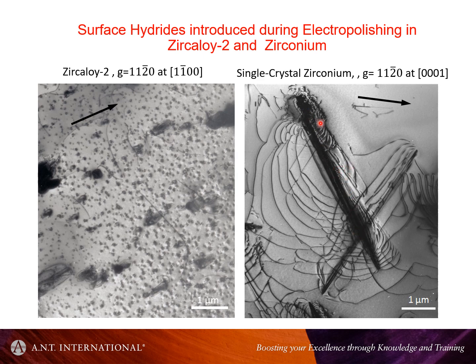The stresses arise because you have a site on the surface which, for whatever reason, is highly reactive, and that's why the hydride forms there: you're creating a lot of hydrogen and pushing a lot of it into the material. So you actually have a source of hydride at this point, and no wonder you get a high stress induced. But that has nothing to do with the bulk behavior of the hydrides. What I've found over the years is that if I don't see somebody say, we know this is not a surface hydride because we did the appropriate stereomicroscopy, I don't believe anything they say.